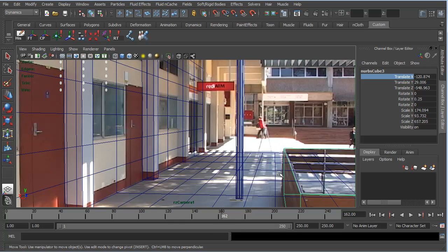So we now have all of this geometry in our scene that represents our background architecture that we have in our footage. And the reason that we have this is not so that we can render this out. Because we have this background footage, we don't want to render objects over it. But what we can do is apply a special material to these objects now, called the Use Background material. And what that will do is show the background footage, but superimpose on top of that things like shadowing and reflections. So we'll be able to fake the casting of shadows on our background footage.